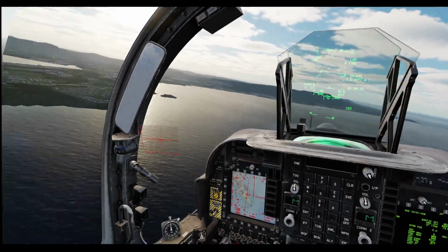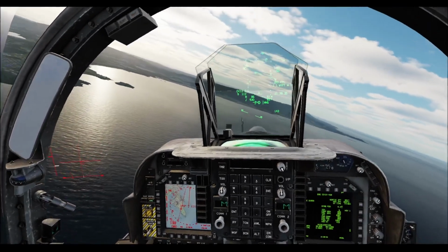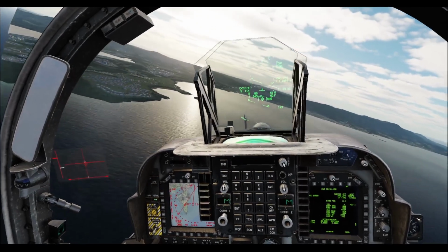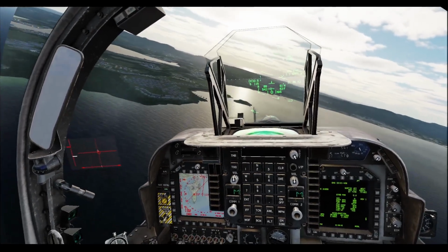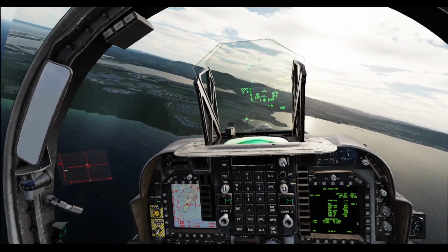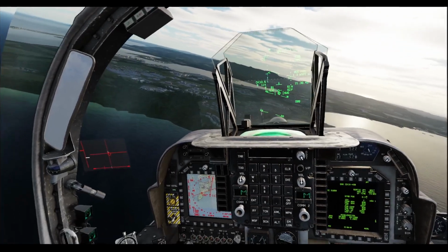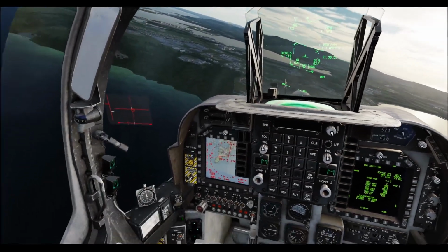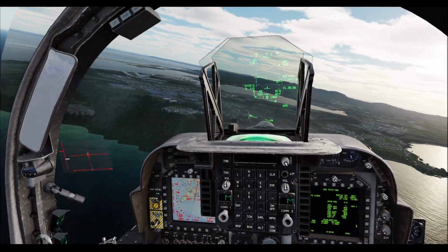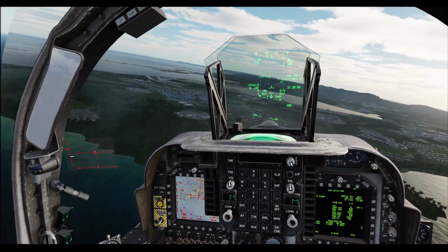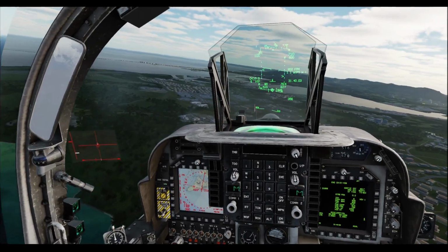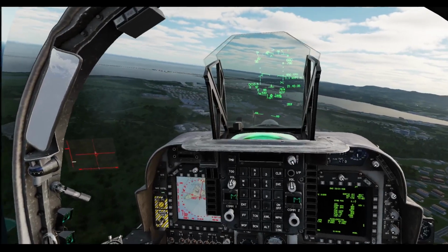And we're going to start our turn now, just in the power, 10 to 12 units of AOA. We're looking to be at 500 feet on the 90. See how high my rate of descent is there. We're a little bit high. We're going to bring the nozzles back to 77 degrees. We're going to add some power.